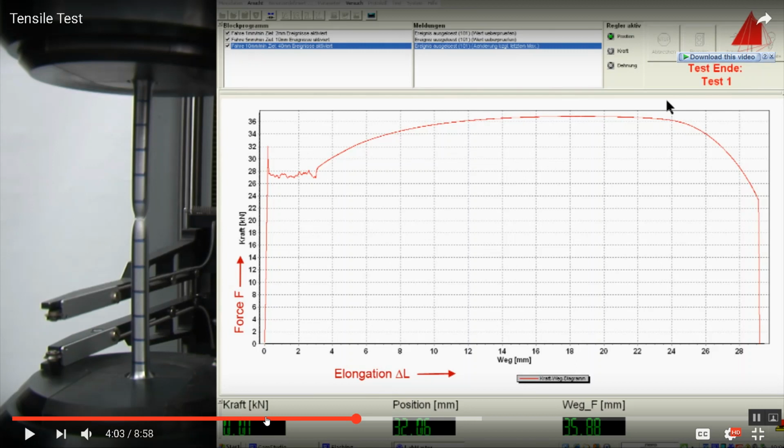Clear? It's very important. So, when we do structure analysis on a beam or something like that, in plastic, acrylic, whatever, to know the safe point from the not safe point, you should know whether this 0.3 millimeter is in the elastic zone or the plastic zone.